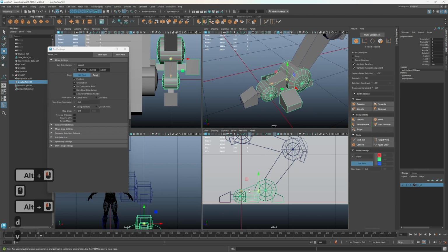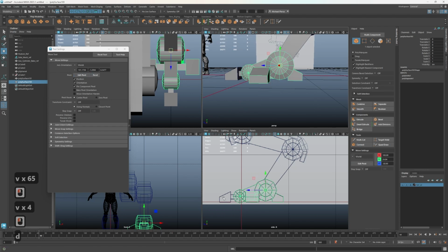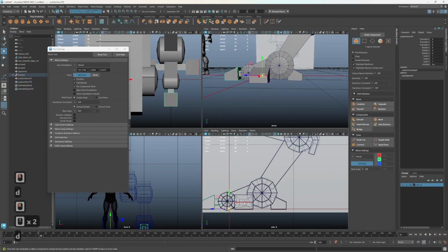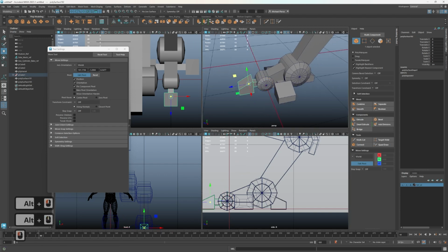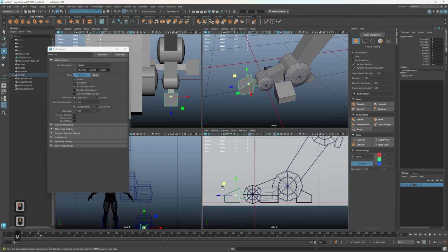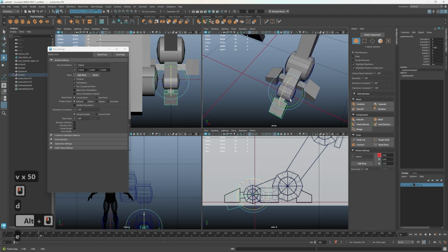Tab D again. You can also grab this arrow, or this one here, because that's 2 axes. And there we go. Then this guy, if I tap D now, I can once again snap that one to the east. Let's first center its pivot, then holding V, I'm going to snap it here. That way, if I rotate it, we've got it rotating around the foot. Perfect.